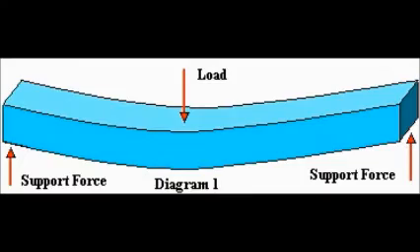Axial stress and shear stress, which develop in a loaded beam, depend on the values of the bending moments and the shear forces in the beam, determining the axial stress, which is often known as the bending stress in the beam, and determining the shear stress or the horizontal shear stress. This is important because of weight. First, it would enable us to know if a particular loaded beam is being underutilized.